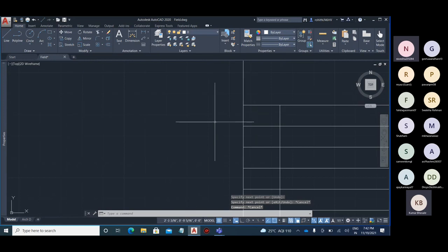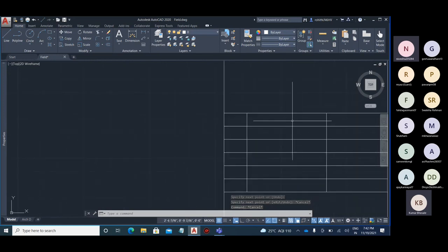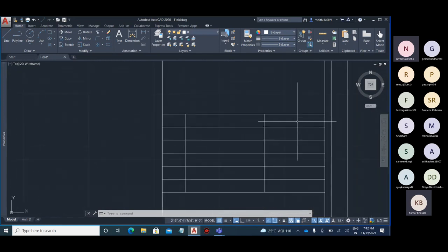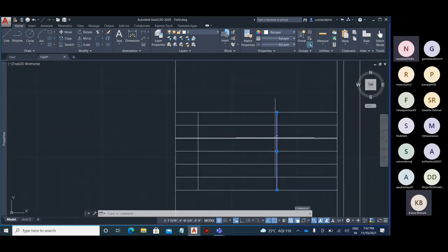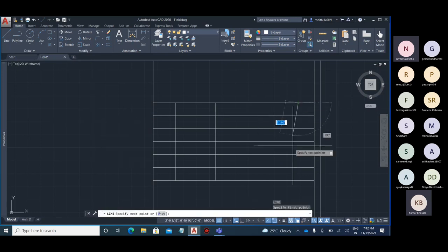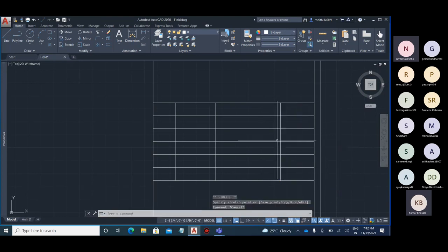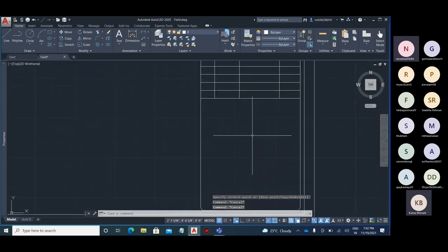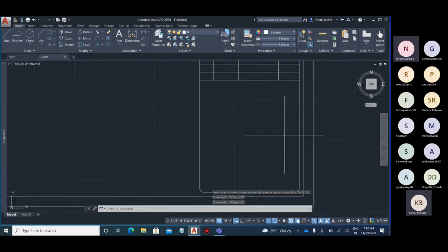So you can have over here number, then the date, and description of a revision number. You can have whatever you want, you can do according to that. For date, let's say I keep over here, and for revision number I'll create one more line. After that, for project name, the space might be over here.